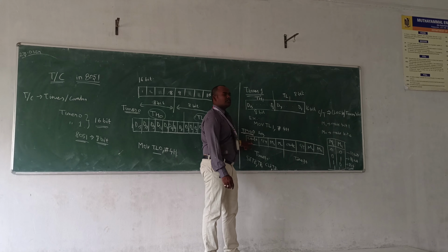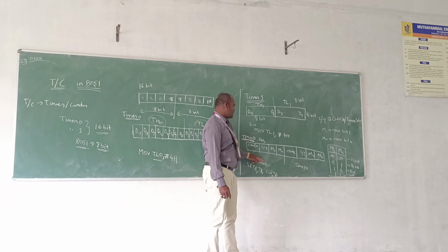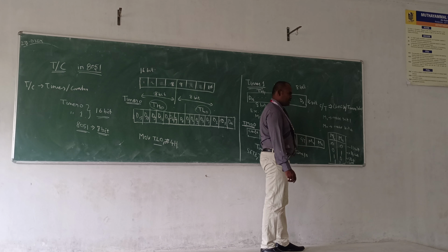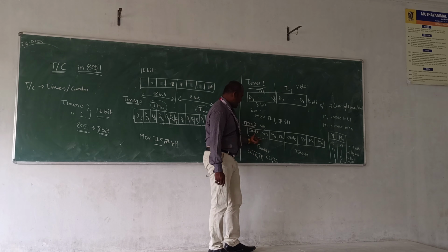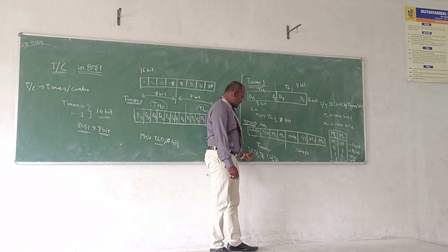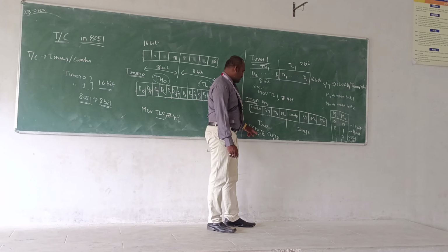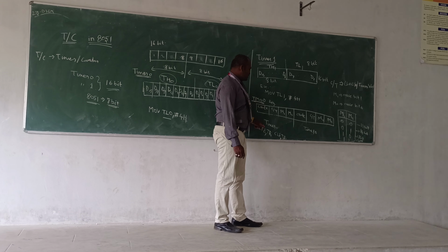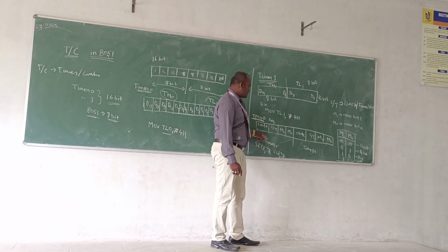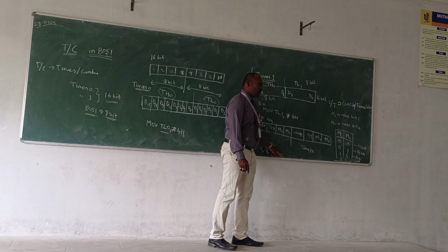The gate may be used to start as well as stop timer 1, and likewise for timer 0. If you want to start timer 1, you can give the instruction SETB TR1. If you give this instruction, timer 1 gets started. If you want to stop timer 1, you can give the instruction CLR TR1.